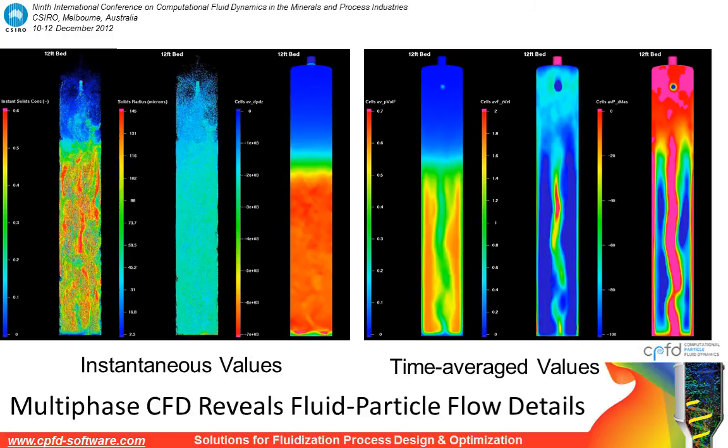Here we're looking at a comparison, all for the 12-foot bed, of instantaneous values on the left with time averaged values on the right. If you are looking at simply instantaneous solids volume fraction, it isn't necessarily really clear what's happening in the bed. But if you do time averaging, as we've done here, you can see in these centerline slices that there is some fairly consistent flow structure forming in this 12-foot bed.